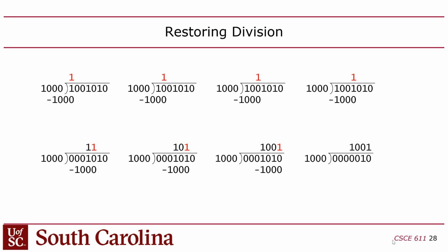What's the bottom line? The bottom line is you have to go through multiple iterations to solve the division problem. So it's basically, remember the multiply is essentially shift and add, right? The divider is shift and subtract, except in addition to having to subtract, there's an extra complication involved where you're subtracting, but you're having to sometimes restore the subtraction, right? Which is why this is more expensive than doing the multiply.